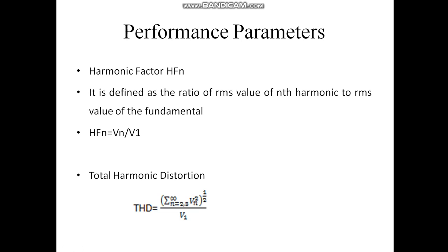It is a very important point. Total harmonic distortion generally indicates the distortion in the waveform. So how much is the waveform distorted? If THD has a value of, say, 10%, then I can say that your output waveform is 10% distorted from your actual or expected waveform.